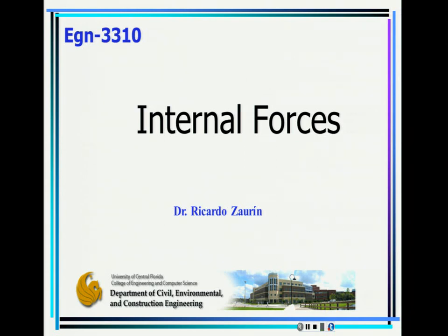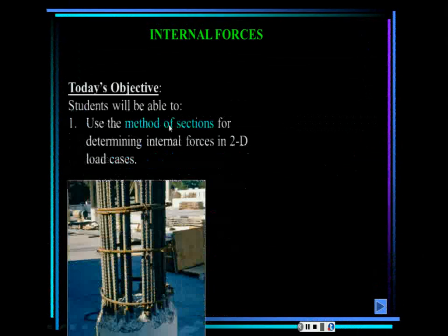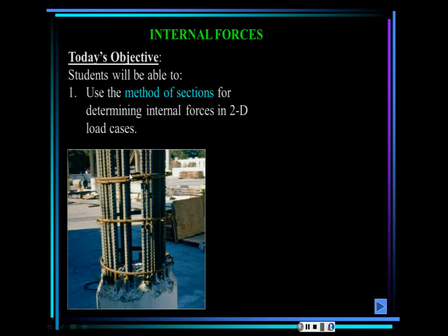When? Don't tell me 3 weeks ago, don't tell me last semester, tell me 30 seconds ago. How come 30 seconds ago? Because when we were solving the problem of the truss, all those forces in the bars are internal forces. They are happening internally in the structure, not externally in the structure. So those are internal forces. We're going to use the method of sections here, but not for trusses in this case. It's for any type of structure, any general structure. We can make sections and calculate those internal forces.